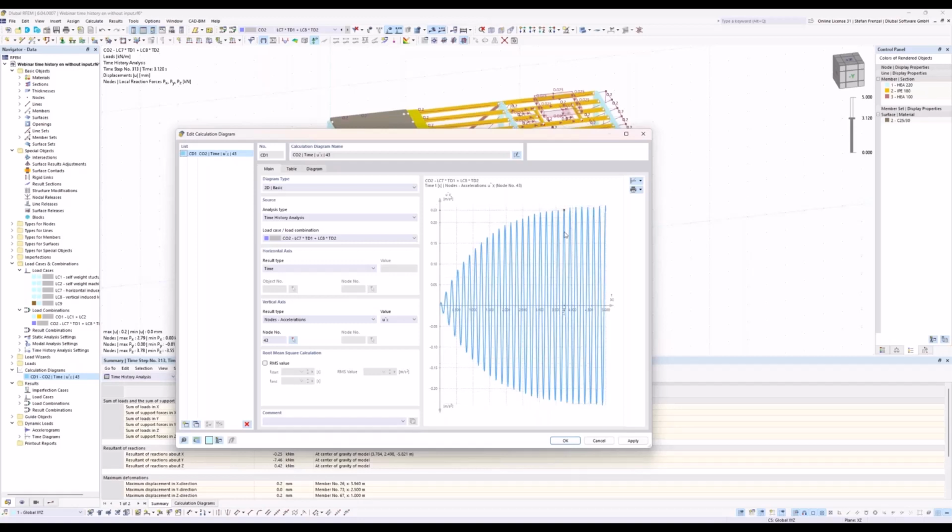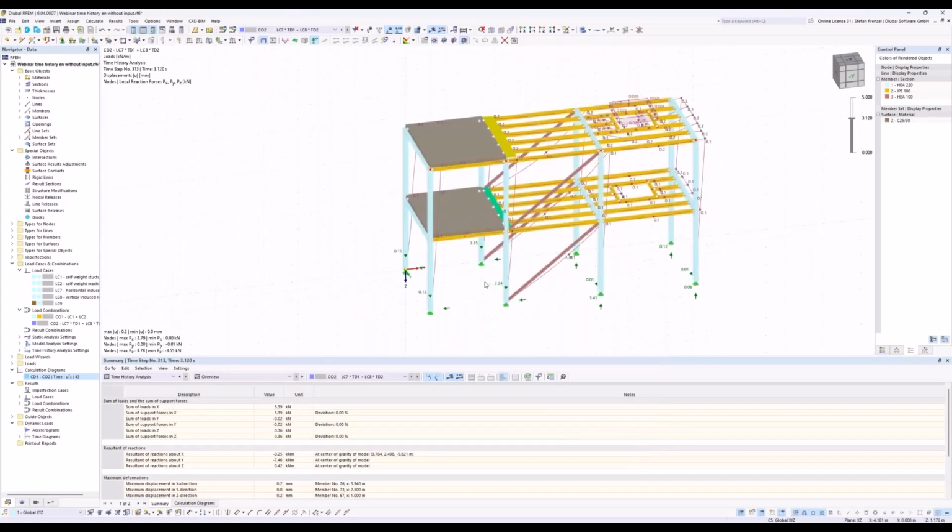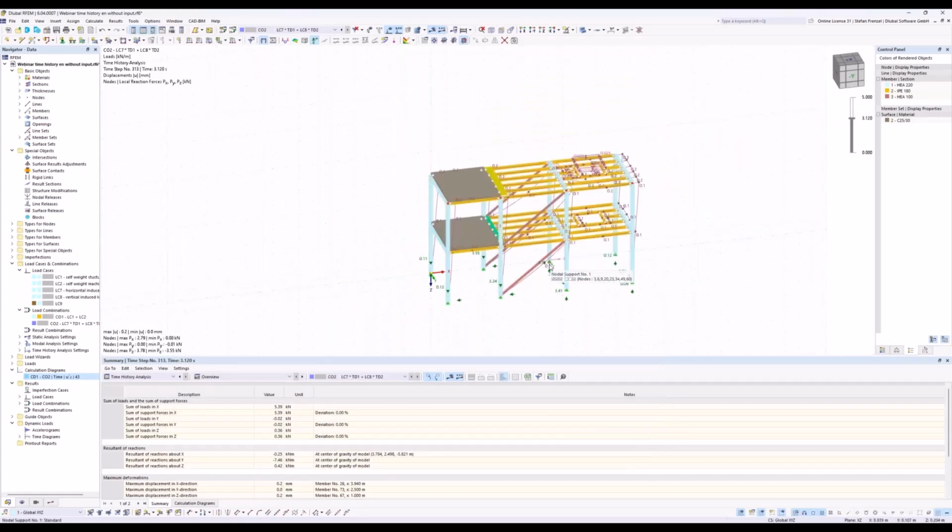That's of course a high value, and that could be, also by using the damping, that it's not sufficient for using the whole building like this. So now we come to the point where we have to optimize normally the structure. One optimization could be we use another machine, because if we have another induced vibration, then maybe it could work. But normally, it's also possible to change something in the structure.